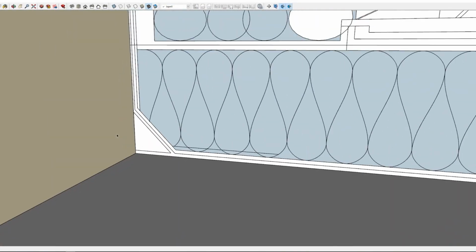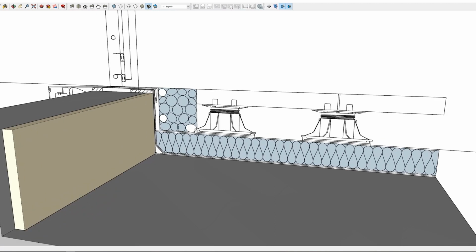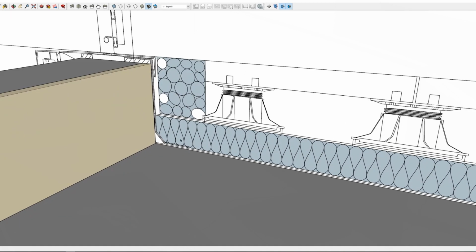And then what that is there, that's a fillet, so that the membrane that's protecting the roof doesn't crack. If it's a complete 90 degrees, that's a weak spot. So you give it a little chamfer there, formed with a plastic or a timber fillet, and then when the membranes are overlapping one another, because there's your main roof membrane, and then another upstand one, and they lap there. So it's just a neater detail.